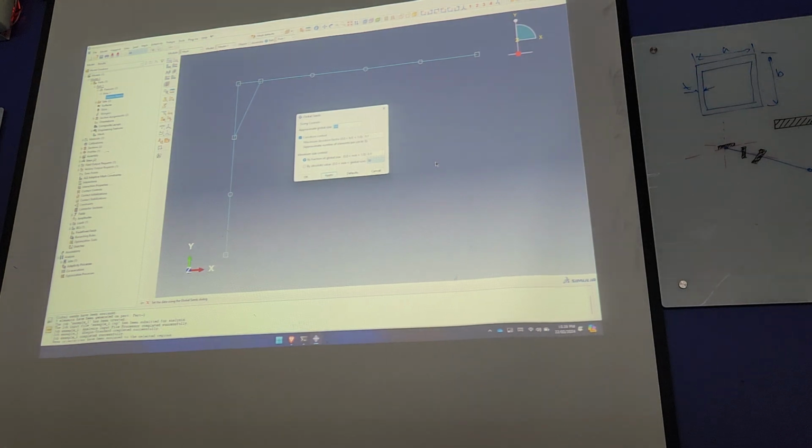Why? Because every point here, every node is free to rotate, yeah? So in our configuration that we have, because this bit here is our truss element, we have to make sure that we've got only one element covering that component.